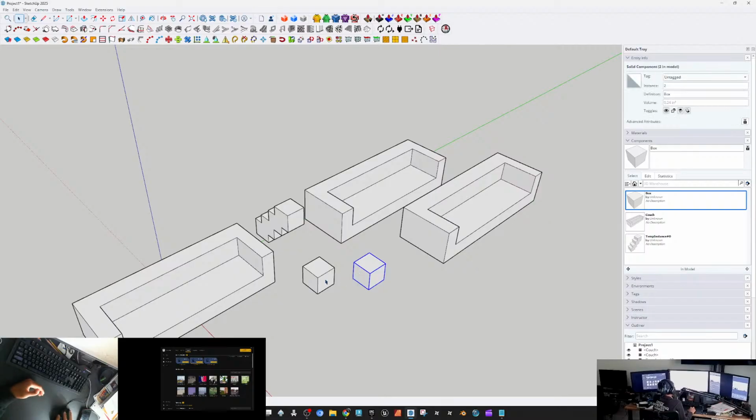Typically when I do instance naming, I will do the main name of the object underscore 2. So instead of just 2, I'll say box underscore 2, or I can just do underscore 2. But I've found that box underscore 2 is more likely to translate over into Unreal Engine in a way that makes it easy for me to find them both in the details panel and inside of my content browser.